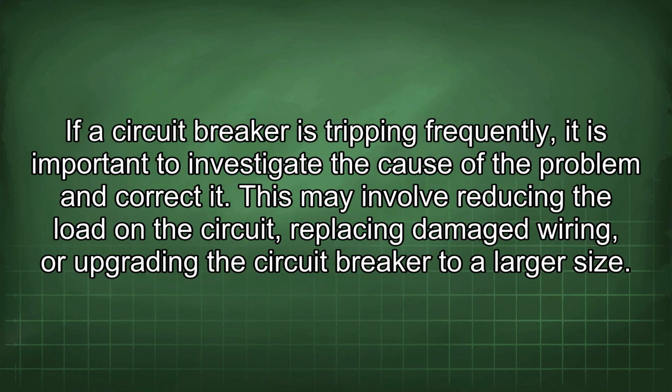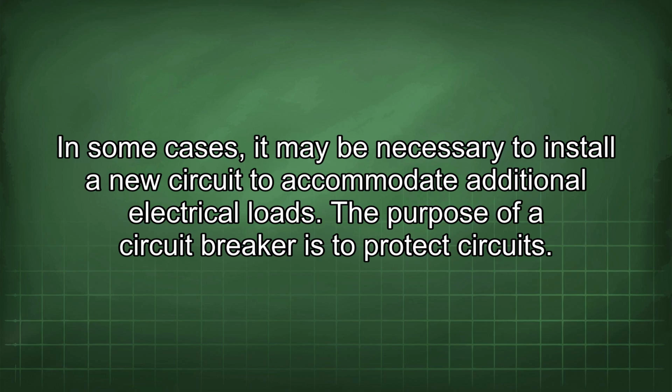If a circuit breaker is tripping frequently, it is important to investigate the cause of the problem and correct it. This may involve reducing the load in the circuit, replacing damaged wiring, or upgrading the circuit breaker to a larger size. In some cases, it may be necessary to install a new circuit to accommodate additional electrical loads. The purpose of a circuit breaker is to protect circuits.